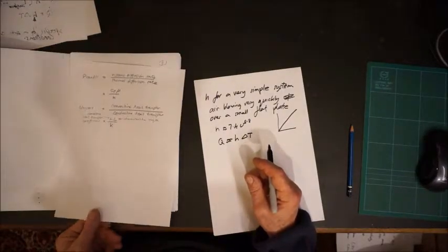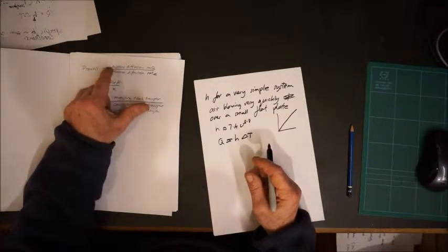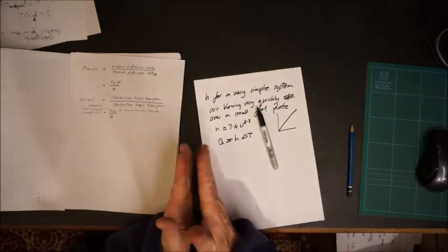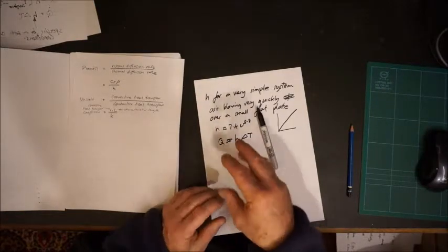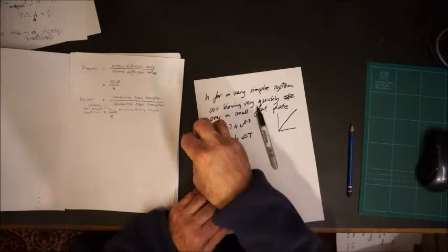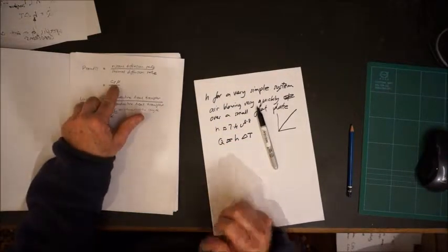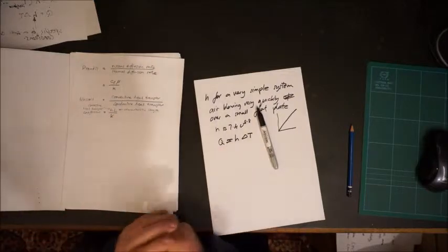So just having a look at these, the Prandtl number compares viscous diffusion over thermal diffusion. In other words, how quickly something is being conducted through the fluid versus how quickly the heat is actually being moved away by the molecules moving. And fortunately we can calculate that fairly easily. It's a combination of the specific heat times the viscosity divided by the thermal conductivity of the fluid.